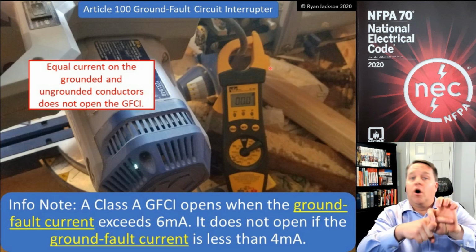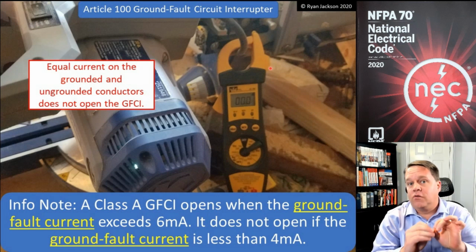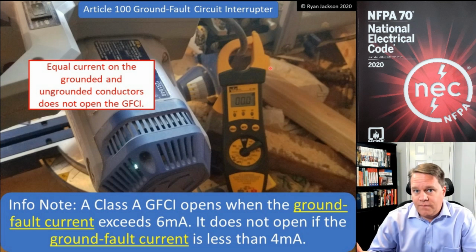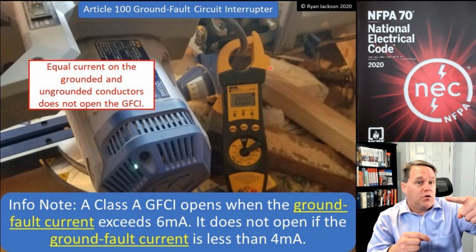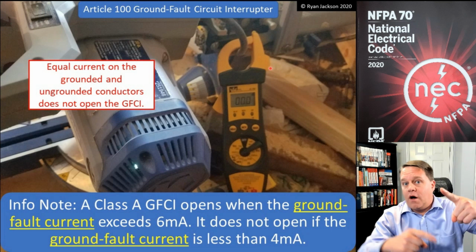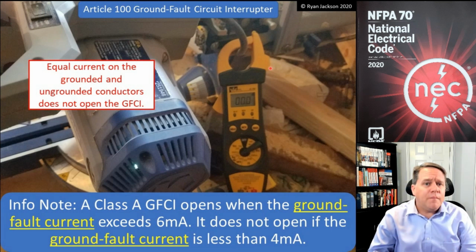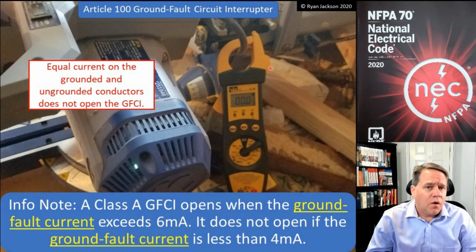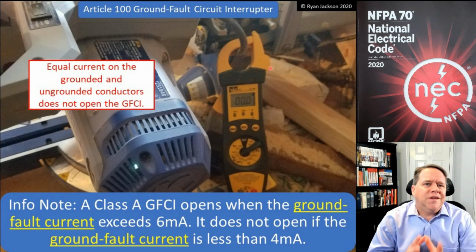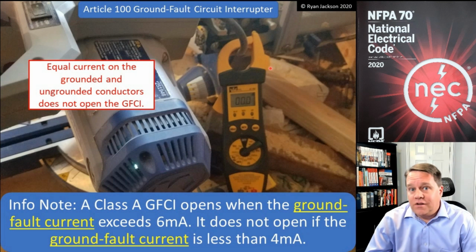So we're going to measure it on the intended path, and as long as those numbers are net zero, then everything is working correctly. But if all of a sudden I have more current on one hot than I do on the other, or if I have more current on the hot than I do on the neutral, that means current is going somewhere that we don't want it to go, and we're going to open the circuit protective device. And that's why you don't need a neutral for a GFCI to work on a line-to-line load, right?